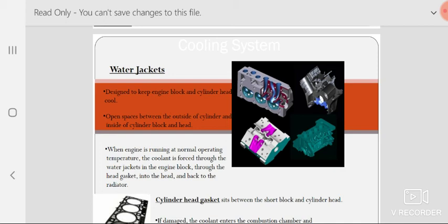See, it goes to the interior of the cylinder. The holes are drilled within the cylinder walls. It goes up to the interior of the cylinder through which the coolant moves. So automatically, these cylinder walls get cooled, and when the engine temperature increases through the cylinder wall, the heat of the engine goes to the coolant. Coolant gets it cooled. This is the way the engine works.